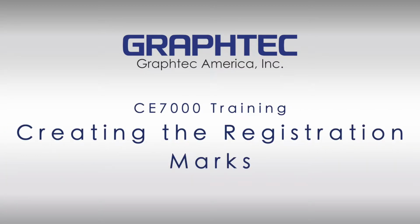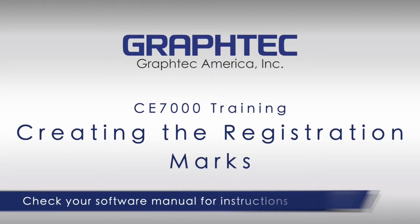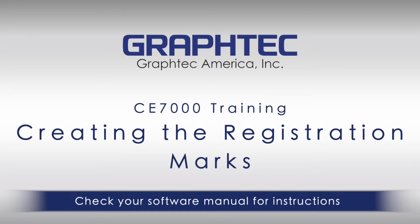In this part of the print and cut segment, we will cover how to create registration marks using Cutting Master 4. While we will be using Adobe Illustrator with the Cutting Master 4 plugin, the steps are generally the same with Corel Draw and with GraphTec Studio applications. If you use a different application, the steps are likely the same, but it is best to check your software manual.